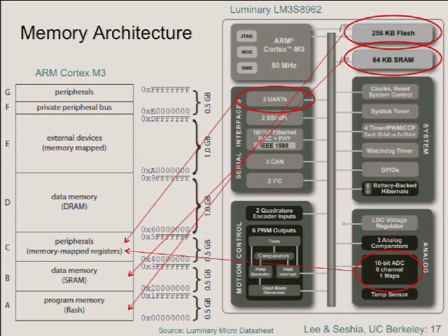Okay, let's go ahead and resume. Just as a last word on memory architecture, I wanted to show you what the ARM memory layout looks like. It's not that different, except that here, unlike the one we were looking at before, the memory space is used for both program and data, the same set of 32-bit addresses. This is a 32-bit processor with 32-bit addresses.